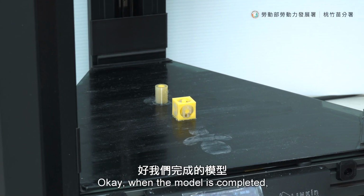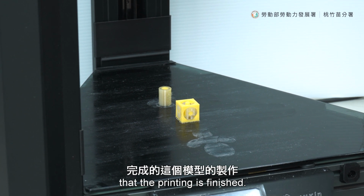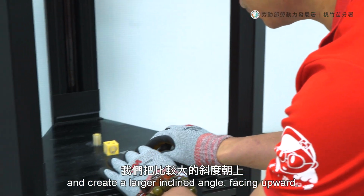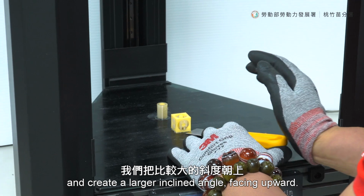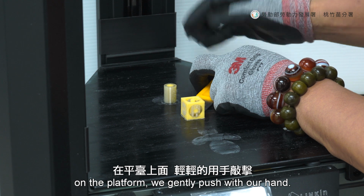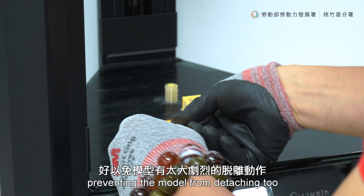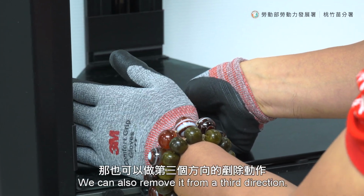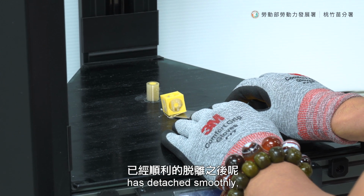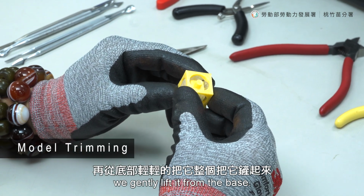Okay, when the model is completed, the machine will give a beep as a notification to us that the printing is finished. Now we take a spatula to create a large inclined angle facing upward at the base of the model. We gently push with our hand. Sometimes we may need to change to another angle, preventing the model from detaching too forcefully. We can also remove it from a third direction. Once we see that the model is detached smoothly, we can gently lift it with our hand.